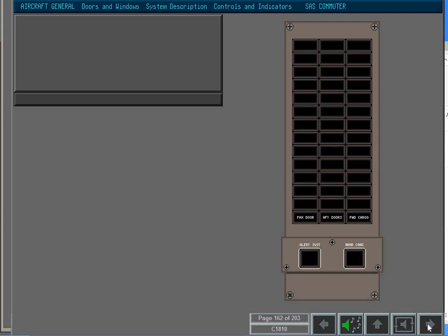White indication lights appear on the central annunciator panel when either the passenger door, forward cargo door, or aft doors are unlatched. If either engine is running with the park brake released and a door not locked, then an amber doors message is annunciated and a level 2 alert presented. Alerts will be discussed in more detail in the Integrated Alerting System module. Note that the white indication lights are always bright regardless of the annunciator light selector setting.